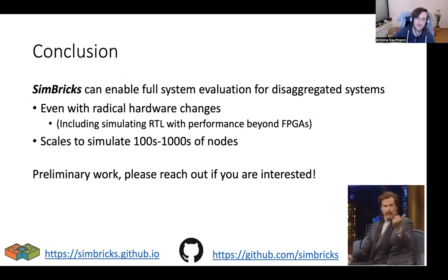If you have an RTL implementation, you could do things like use FireSim, which uses hardware to accelerate the simulation. But in that case, with FireSim, it's still a simulation, so you can still control how fast the clock on that circuit is running with respect to the other bits. But if you have a real piece of hardware, that's just going to run as fast as it's going to run. Typically, the relative performance of that would be much higher than whatever you're simulating in software. That might be okay, but usually that's going to be a problem. It's going to throw things way off.